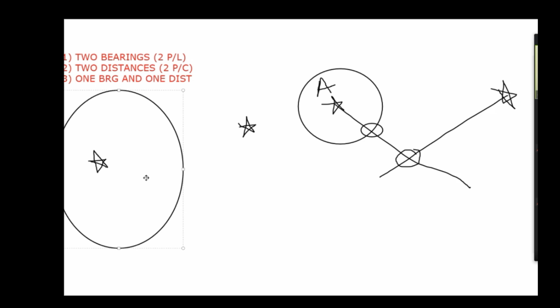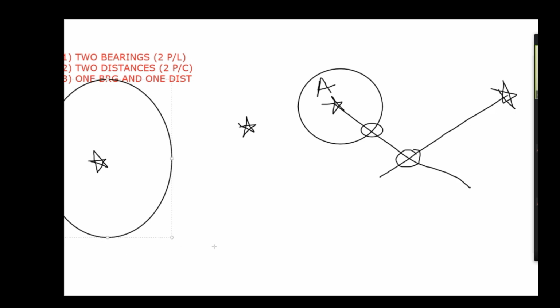So all this reasoning we will give, and we will cancel one. One PC we get from one lighthouse, the other PC, the position circle, you get from the second lighthouse, and the intersections give you two positions.